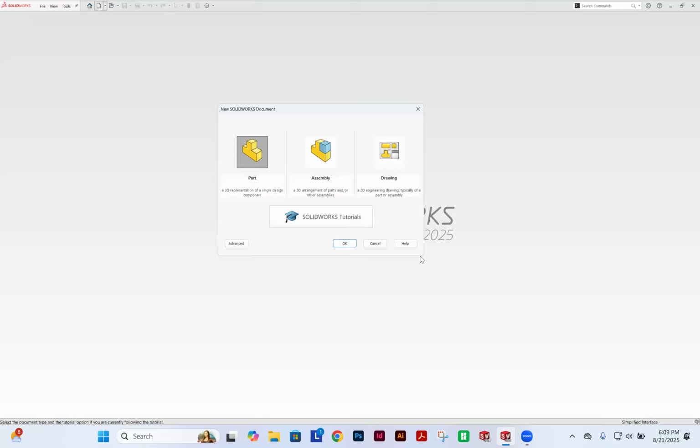These are all the individual parts. Although what we did, which still makes the most sense when you know you're going to have a lot of parts that all need to fit perfectly together, we built this as one part file comprised of about 10 different solid bodies. That's still the smartest way to build when you know things have to have perfect tolerance from piece to piece